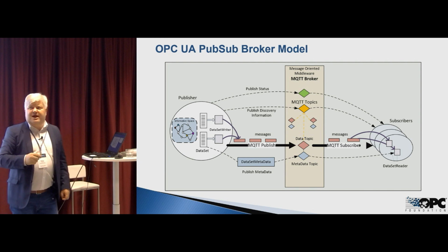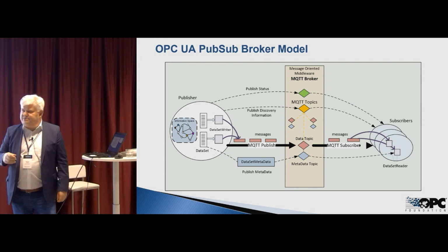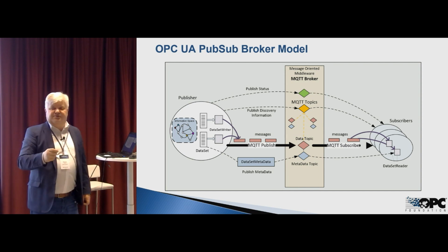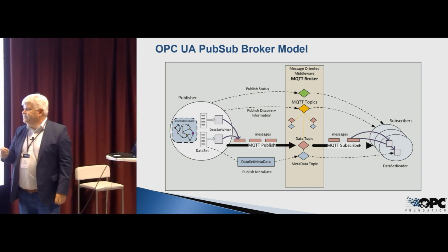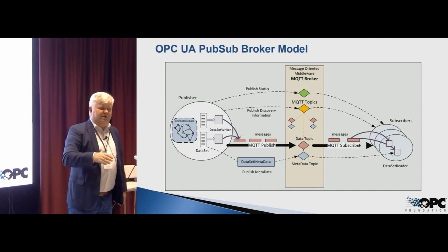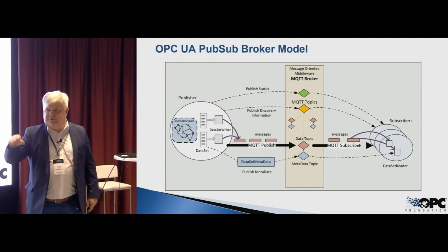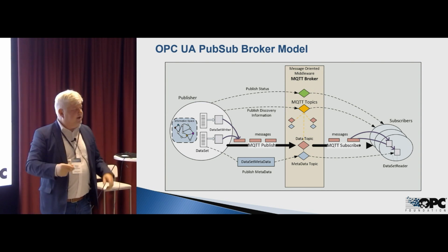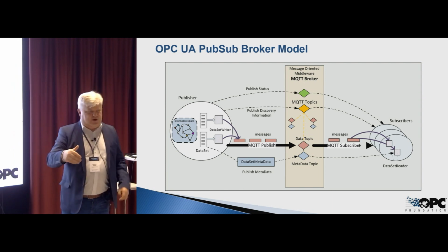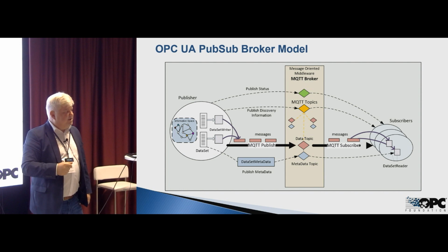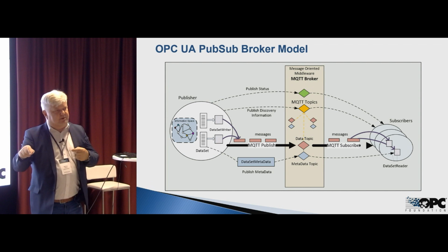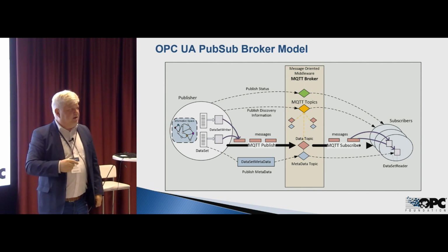So what we added now is a so-called standard topic tree namespace for OPC UA. The main use case is discovery. The data topics can also fit into that standard tree, but you can also still reference other, custom trees for the data topics. But the idea is that at least discovery works with a known topic tree, and if you have the discovery information, then you also know where the data streams are located, so the topics for the data streams.